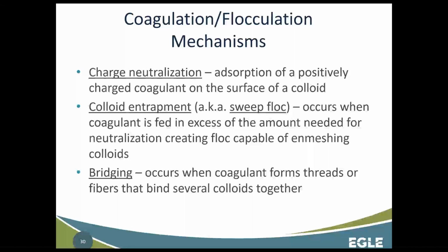We have pin floc when the charges are neutralized. We start getting these flocs enmeshed into these large sweep flocs. That's what we're referring to as colloid entrapment. And now the last step here is bridging. This can occur when the coagulant forms threads or fibers that bind several of the colloids together. So this is beneficial because it helps it resist shear forces.